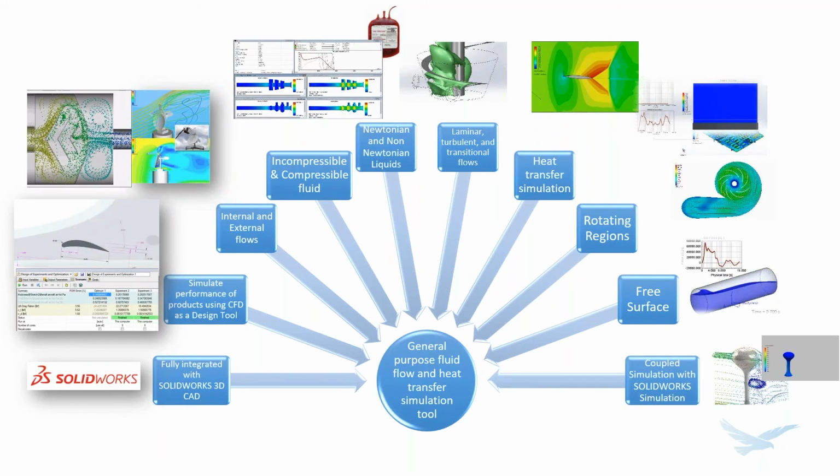The other one that often gets overlooked that I really like to point out is the integration between the CFD tool and the finite element analysis tool, SOLIDWORKS Simulation. So if I were to take something like fluid pressures or thermal results from SOLIDWORKS Flow Simulation, I can actually port those over to the FEA tool.